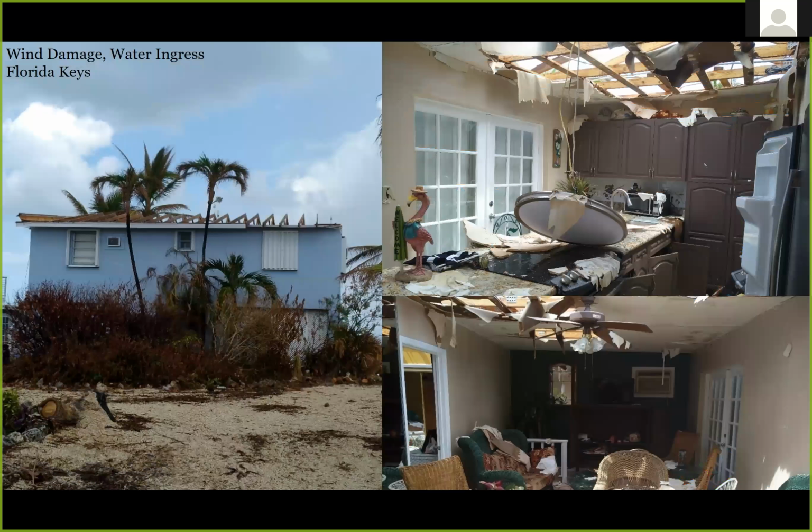All right, and just to mention one thing here, there are plenty of findings I could bring out, but I just wanted to pull out one, which is how common it was to see the effects of water ingress with wind damage. You see the home there on the left. The structure itself is mainly intact. The roof sheathing is completely gone, and the water ingress that results from that completely destroys the interior. In all likelihood, this home is probably going to have to be either completely rebuilt or undergo extensive remediation because of the water ingress.